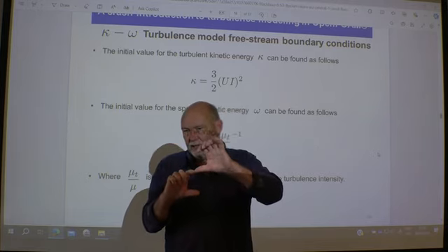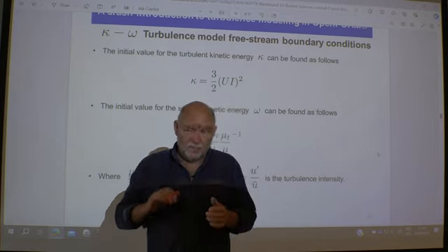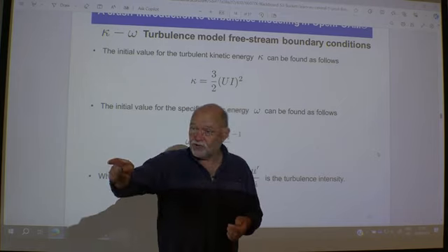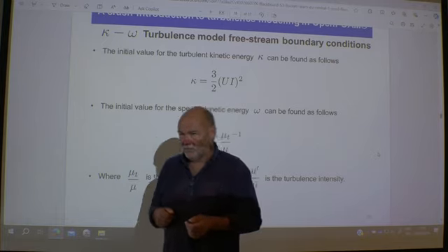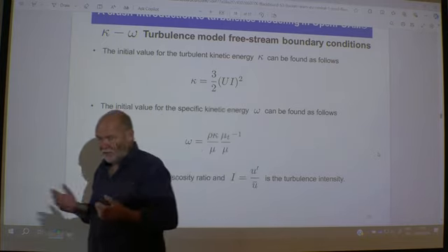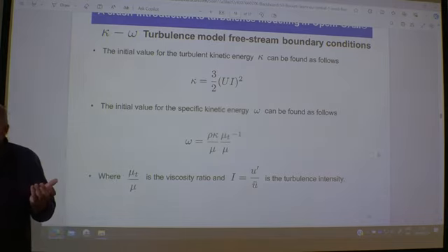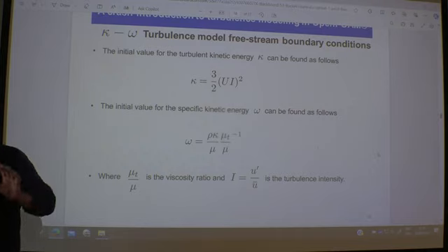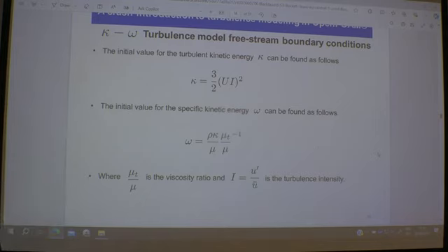You can double it. He will still handle it. Maybe not so good. You have to check it, investigate it, find out. You have to play around with the mesh and see, does my solution change? If I change the mesh, then you're in trouble. Which solution is right? Your headache. But it should be smooth. Other questions?